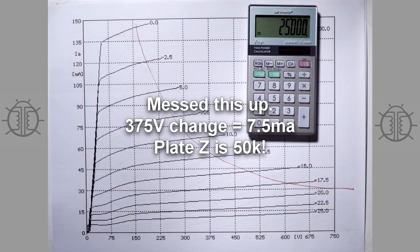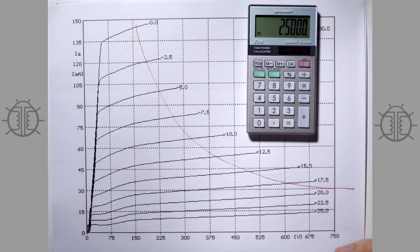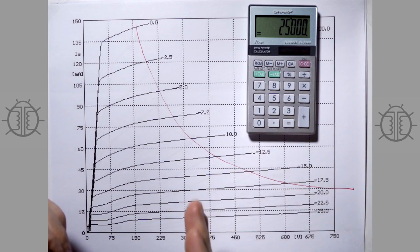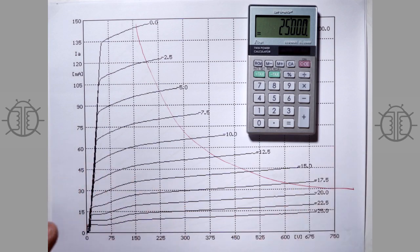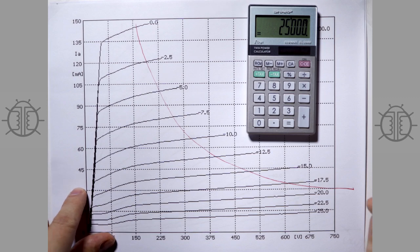And you can see that now the voltage gain of the tube is no longer really that interesting. Now the primary factor of the tube is its transconductance, because the plate voltage no longer really changes the conductance of the tube that much. It's all about the voltage differential between the cathode and the grid.